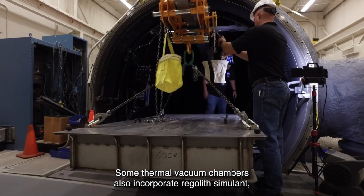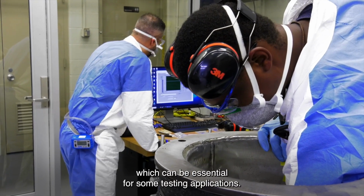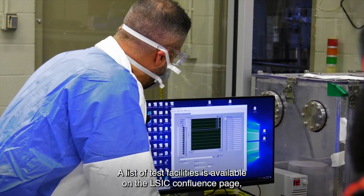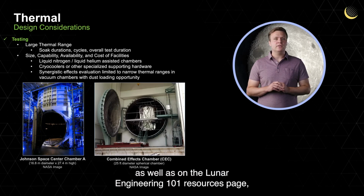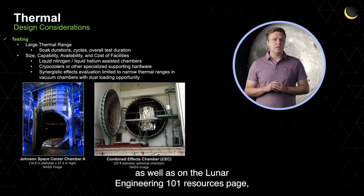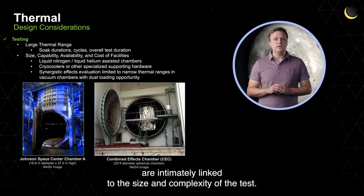Some thermal vacuum chambers also incorporate regolith simulant, which can be essential for some testing applications. A list of test facilities is available on the LSIC Confluence page, as well as on the Lunar Engineering 101 resources page. But be aware that chamber cost and availability are intimately linked to the size and complexity of the test.